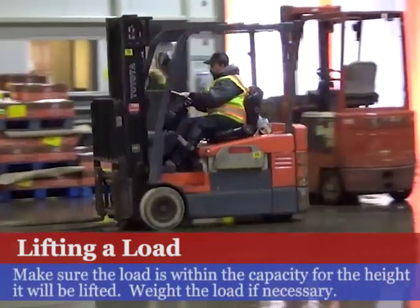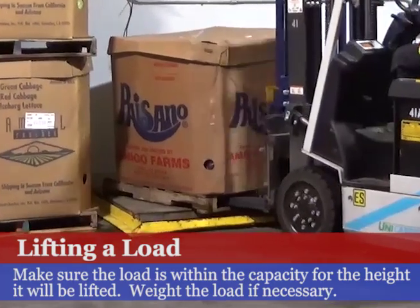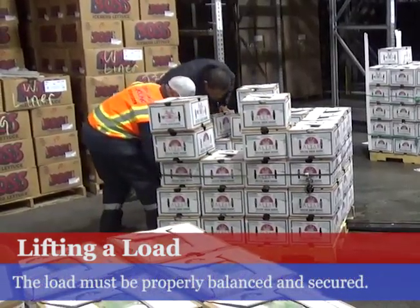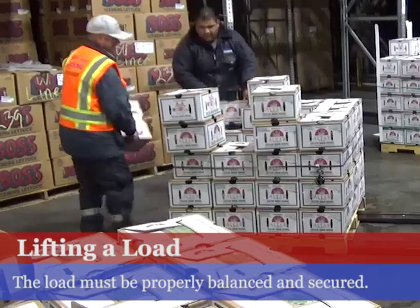When picking up a load, make sure it is within the capacity of the forklift. If you are not sure, you should weigh the load. Make sure that the load is balanced and secure. The shape of the load will affect its center of gravity. You may have to reorganize it, or secure it in some manner, to prevent it from shifting.